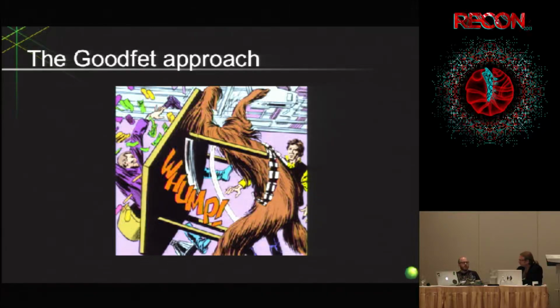What we mean by that is, the GoodFET is a fantastic piece of hardware, we use it for all kinds of stuff. It's not extremely accurate. If you're looking at the wave that's coming out the backside of this, at least in our experience, it's hard to make it line up correctly, especially when this thing's running at 10 megahertz and that's running at 16 megahertz.